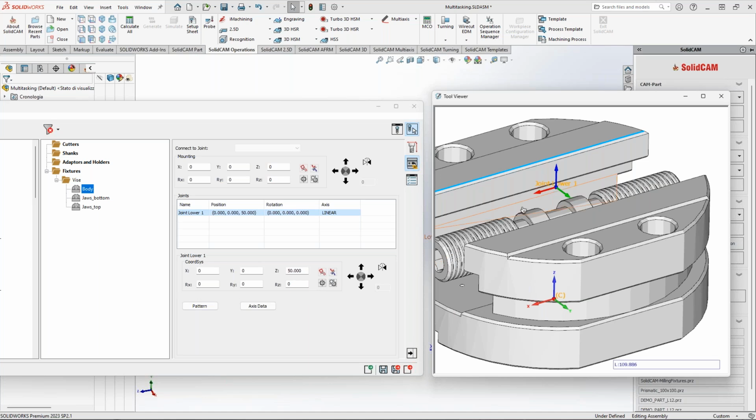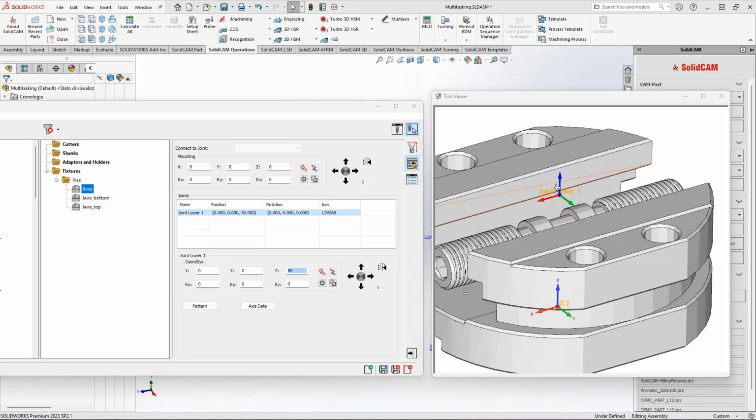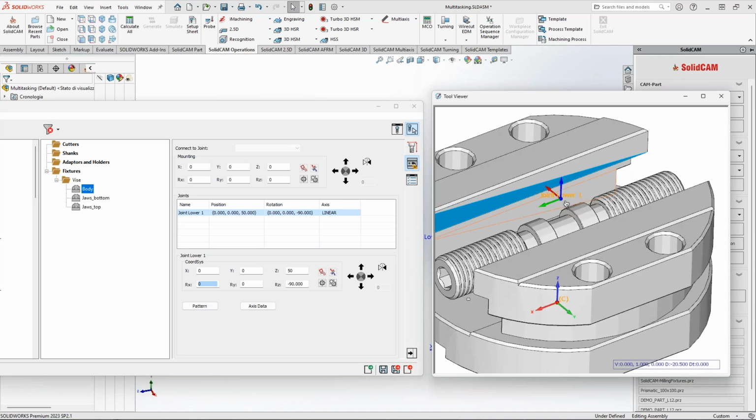Almost the same works for the rotations. So for instance, I would like to rotate my x-axis towards this over here. Of course, I could do it by rotating around the z, sure. But for me, it's easier just to pick on my x-axis and just click on the surface. There you go. Rotation is automatically applied. If you want to reverse it, you can again click on this and repeat it. It will reverse the orientation. You cannot do it multiple times, so it's not working according to your previous local coordinate system; you can only apply it once. I think it's quite good and quite enough.